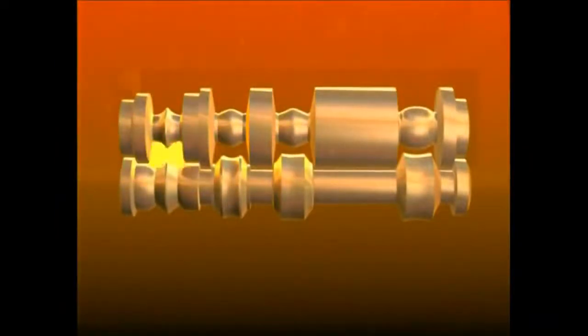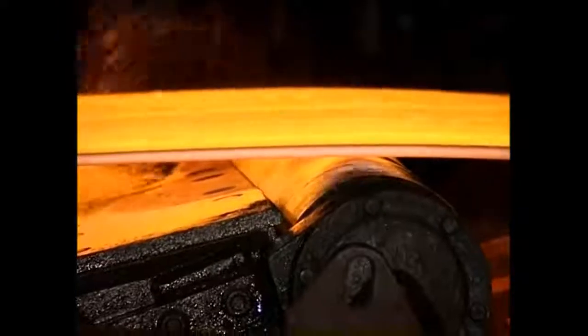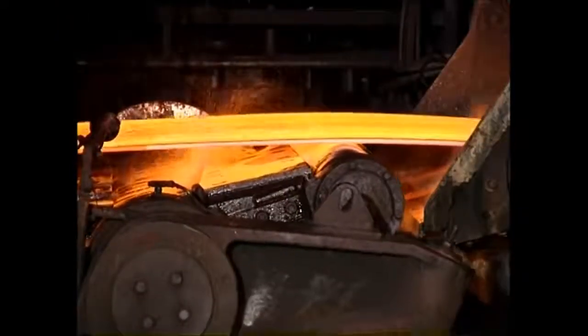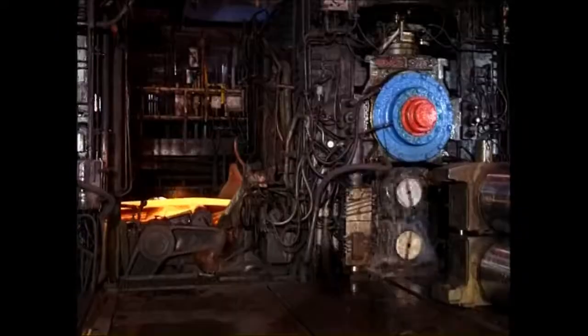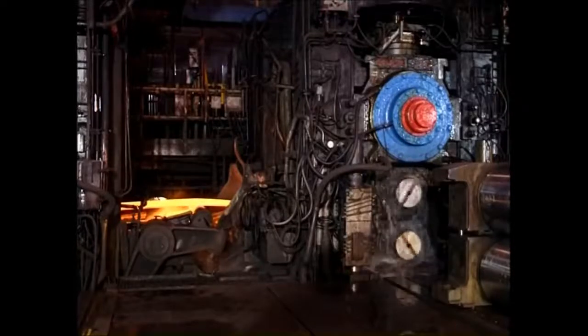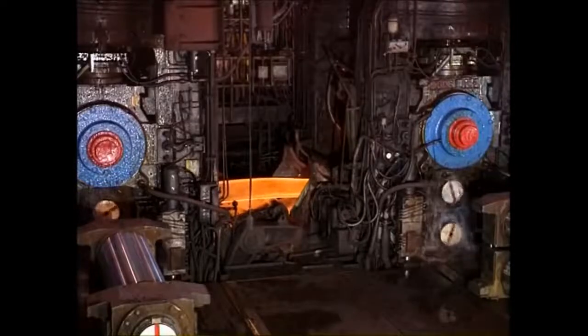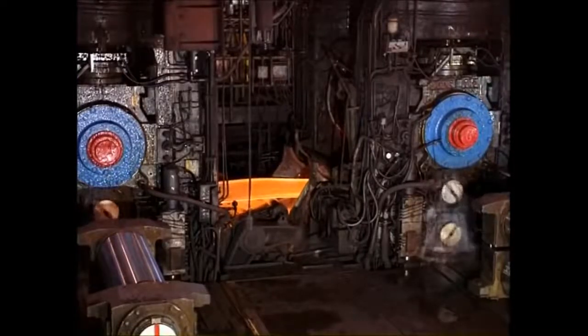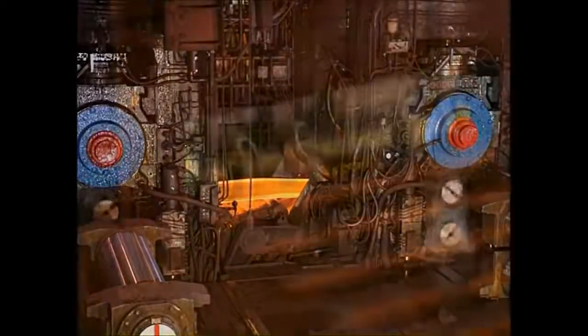Whatever the product, the principles of hot rolling are the same. Steel is squeezed between rolls until the final thickness and shape are achieved. To do this to steel, the rolls must exert forces of tens of millions of newtons, equivalent to the weight of thousands of tons. So the rolls run in massive bearings mounted in housings of great strength and driven by powerful electric motors. These are known as mill stands.